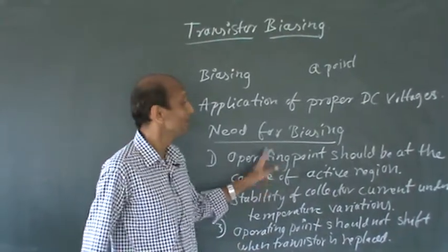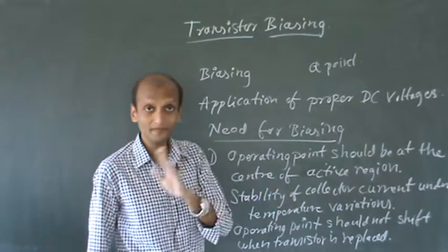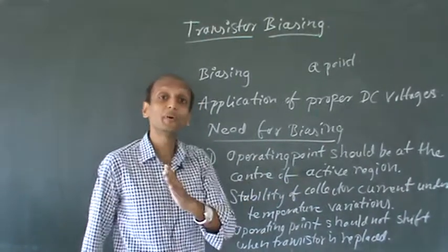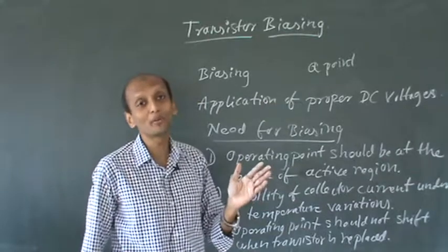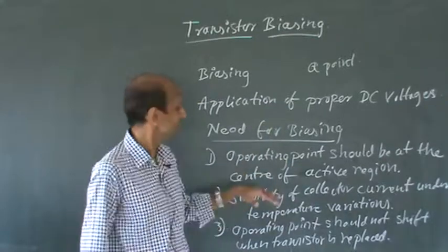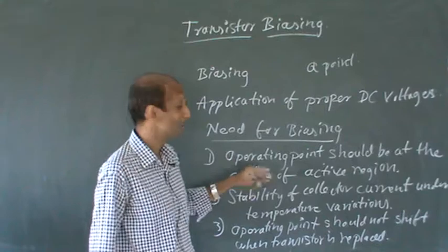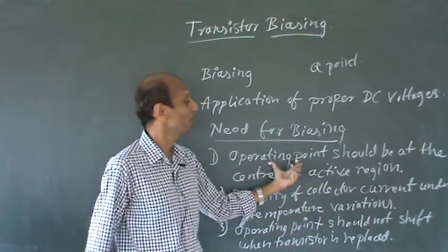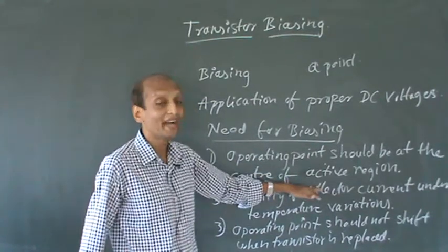So at that time the operating point should not shift, or it should not be going to cutoff region, or it should not be going to saturation region. Okay. So that is the point over here. So operating point should be at the center of the active region.